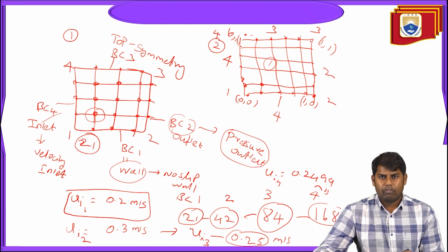So when we change the number of grid points, if the simulation results change, then whatever grid points we take are inaccurate, and the simulation has to be continued until grid convergence has been reached. Convergence of the grid point means that as we change the number of grid points, if the simulation results do not change, we take the lowest count of grid points where the simulation results have reached the steady state.